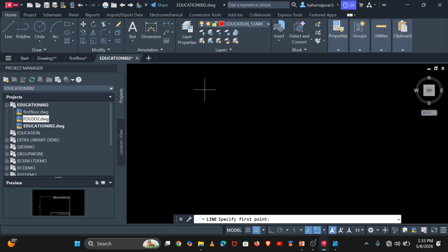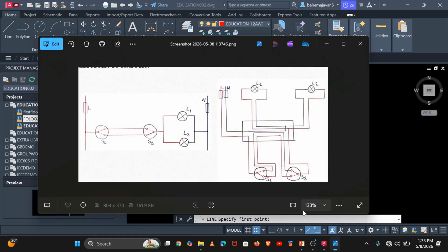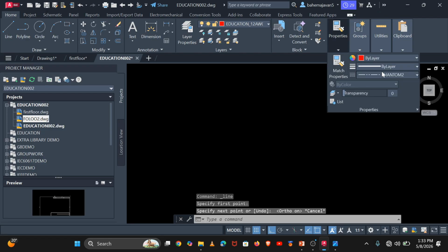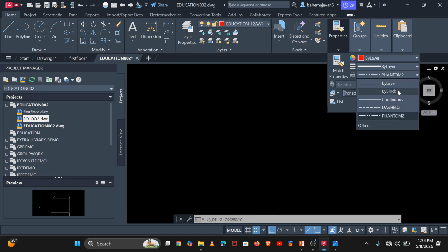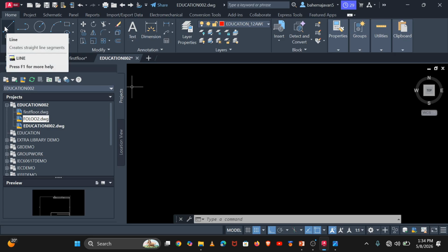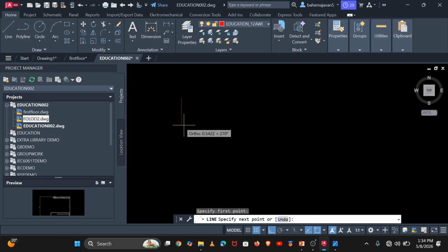you grab a line, and here you see the drawing shows that we must come from here, make an angle of 90, then downward again another angle of 90. So we do it like this. Let us turn on orthogonality. Sorry, you can see we are using a dashed line. Let us escape from it and use other properties and choose the solid line like this one. And after, you can see that it has changed from a dashed line to a complete line.